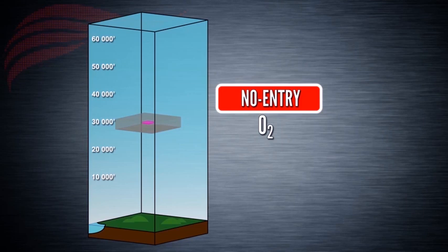Let's perform a similar analysis with the total air pressure at sea level of 1,013.25 hectopascals, as opposed to 265 hectopascals at flight level 330. If we convert both values to psi, or pounds per square inch, at sea level, the pressure is 14.7 psi, as opposed to 3.84 psi at flight level 330.